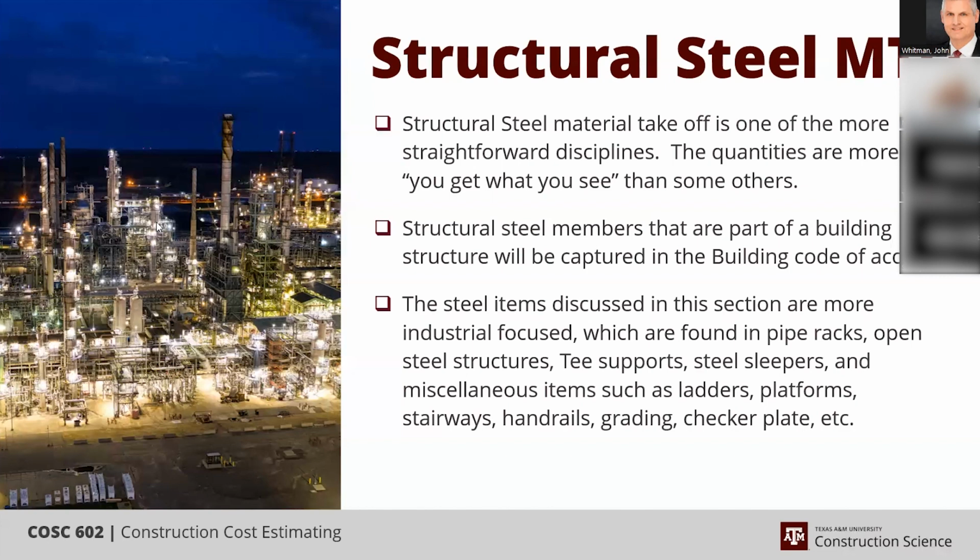But a lot of the time, the reason that there's an open structure is to elevate other pieces of equipment in relationship to that tower, because there's a process requirement for only so much head pressure entering that piece of equipment, or that needs more head pressure as an exit. And so it's using the elevation to add that head pressure to the process fluid. There's a number of reasons, but a lot of our heavy steel is involved in these open structures.